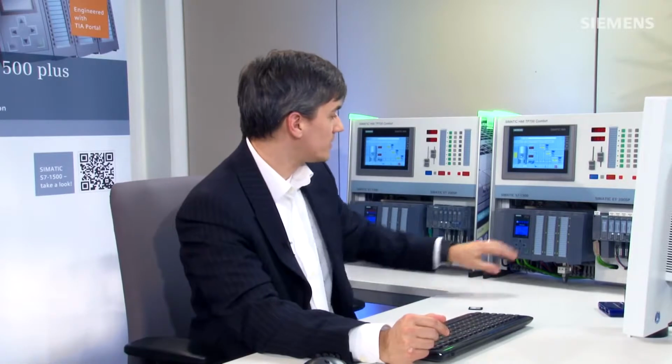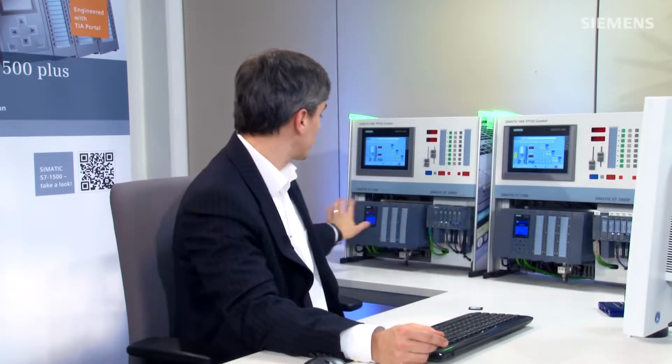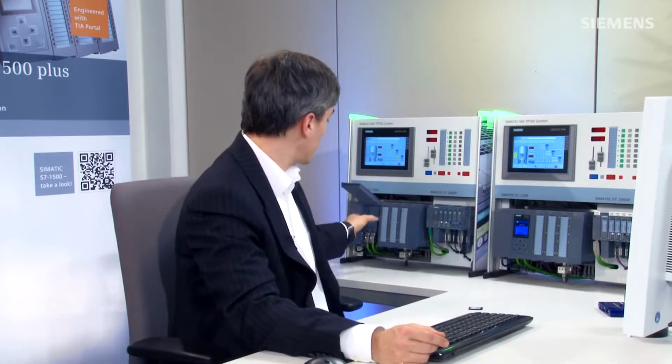As you can see here, I have the S7-1500 with some local I/O, ET 200SP distributed, and a Comfort Panel, all of which is on Profinet. I've also got a memory card, which is required for the S7-1500, where I have the configuration and the code located. Right next to it I have the exact same configuration, however I have no memory card and no code. So what do I want to do? I want to protect this card from being copied.